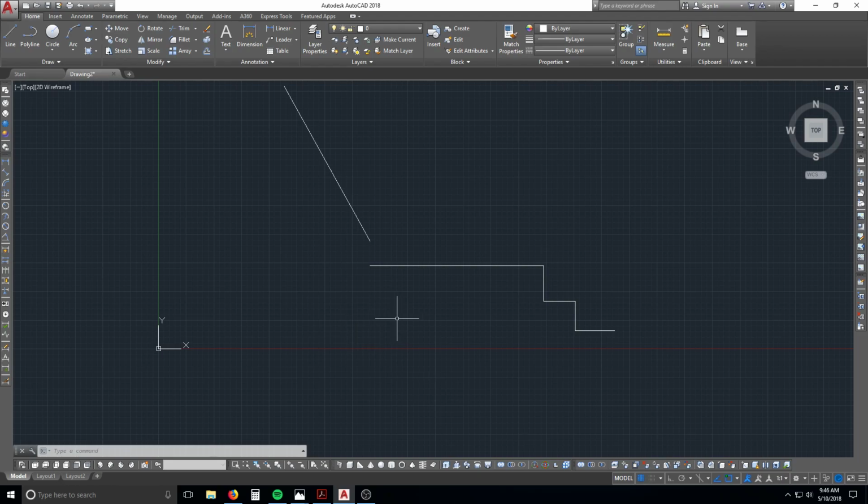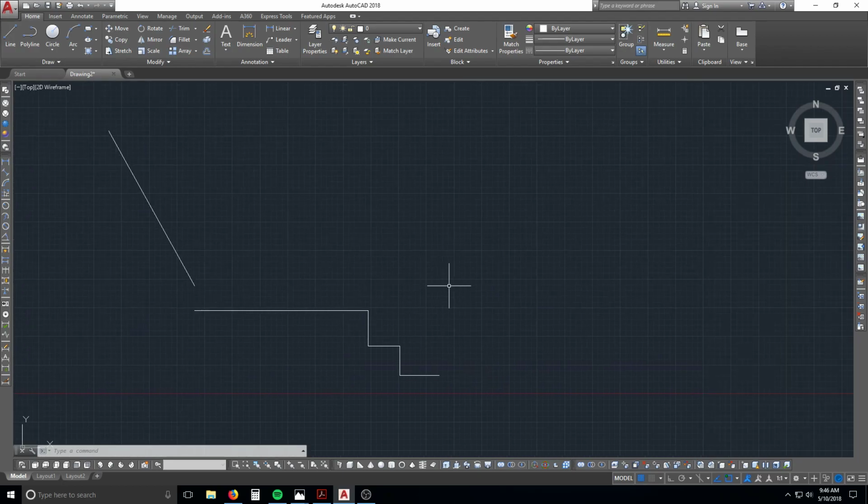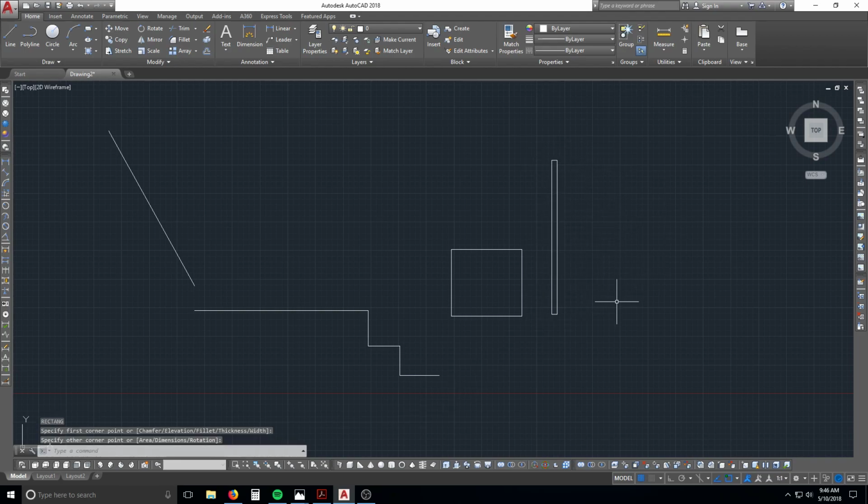The next one is going to be rectangle. Now we're getting into utilizing more of a polyline kind of command, where it's REC for rectangle, and then enter or spacebar, left click and drag, and left click again, and there you go. If you hit enter, it should still remember the previous command. Again, it does rectangle, and I can go from here to here if I wanted to make it any shape that I wanted. There you go. Now it's a left click and a left click.